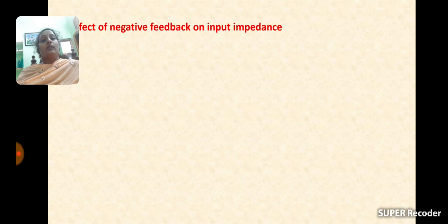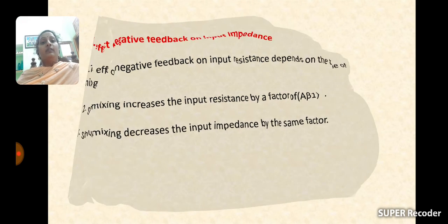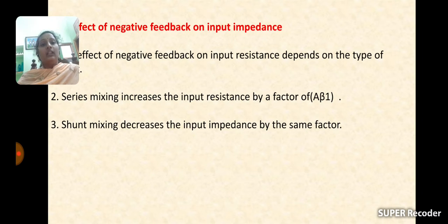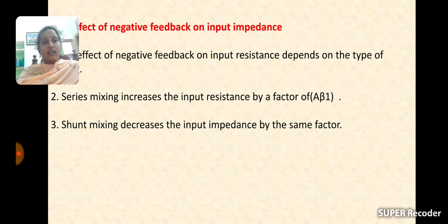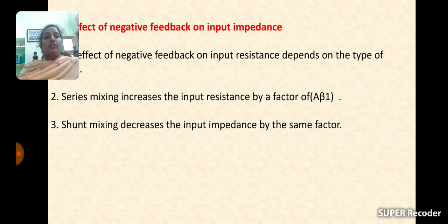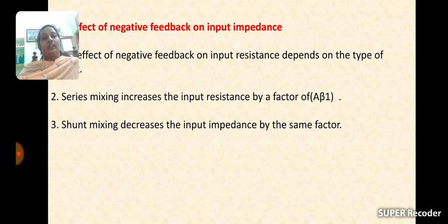Coming to the next one, the effect of negative feedback on input impedance. How will negative feedback affect the input impedance? The effect of negative feedback on the input resistance depends upon the type of mixing. Type of mixing means whether positive is connected to positive or positive is connected to negative.